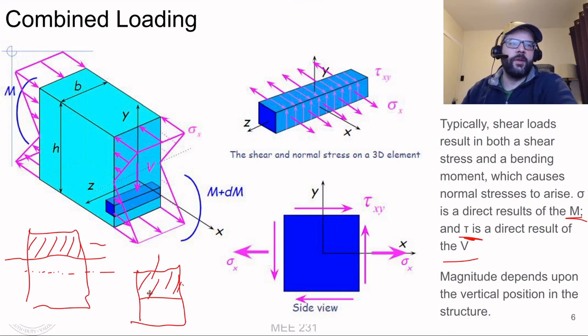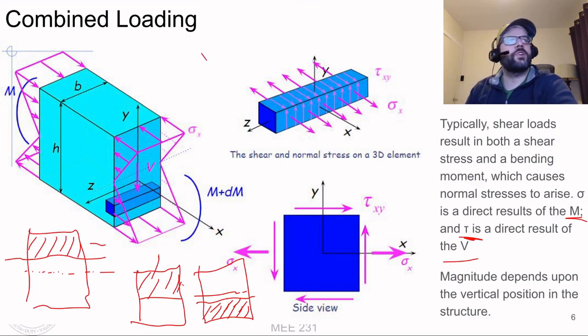And then, of course, if we're below the neutral axis, so if this is the neutral axis and this is the line we're looking at, we shift to the area below the neutral axis, the area kind of separated from the neutral axis by that point. So you tend to get, at least with members of a constant cross section, a quadratic formula that gives you the stress variation as a function of the vertical position.